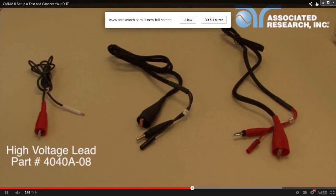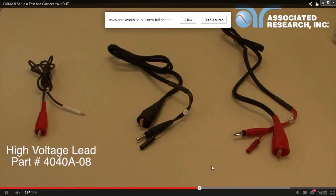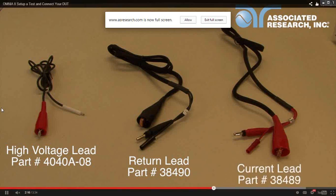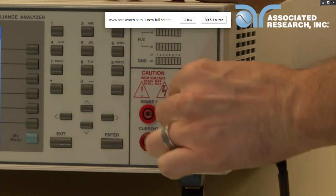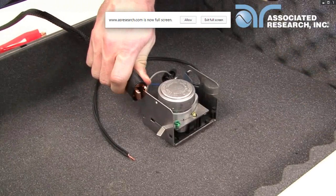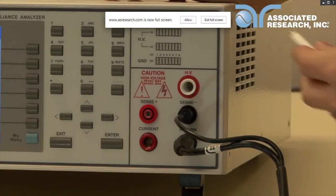In this video, we're going to look at how a high voltage high pot test and a ground bond test can be performed. What we're looking at right now are the cables that will be used for this test: the high voltage lead, the return lead, and the current lead for the ground bond test. So here we are connecting the return lead to the return side of the high pot tester, and this return lead is being clipped onto the chassis of the product under test.